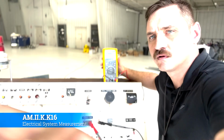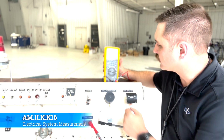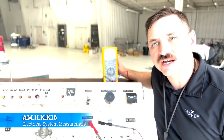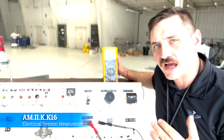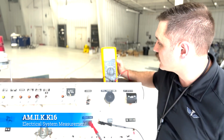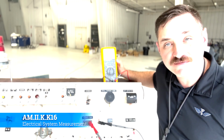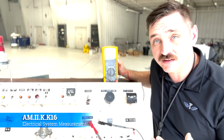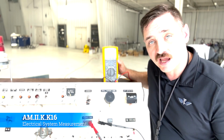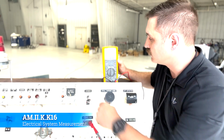All right, so one of the first things that we can do is to just see if we're getting continuity through that light. All right, so we see that we're getting 48.85 ohms. So we're showing that there's continuity through there, but it's really, really high. But we would expect that because there's a light bulb there. Kind of a good way to check that is just simply remove the light bulb.